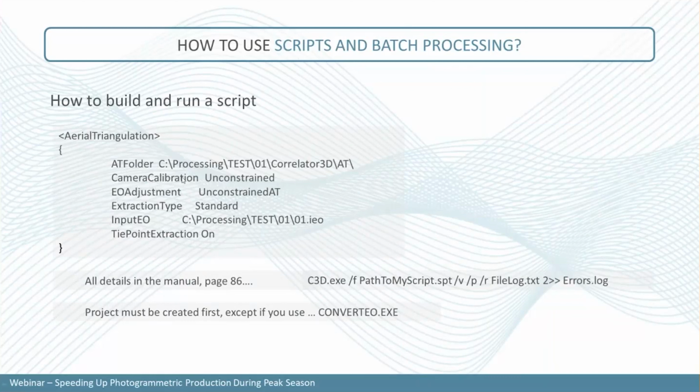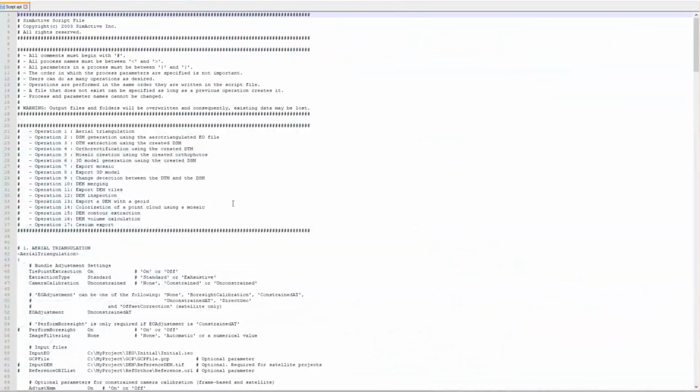changed within the script. If you want to start building a script, we have all the modules already pre-scripted. If you go into the Tools, Sample File menu here, we have an example of all the tools that can be scripted.